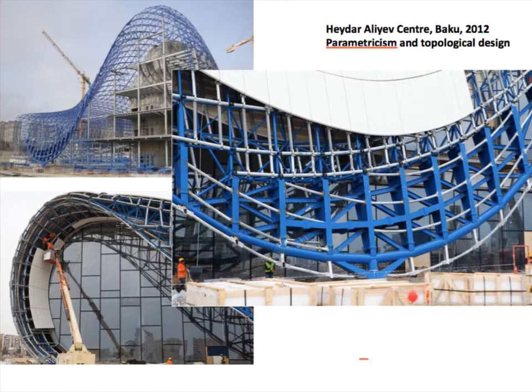It is, however, made from steel, a material that is around 7 times stronger than reinforced concrete. If it had been made in reinforced concrete, as the CNIT shell was, the equivalent thickness would have been 420 millimeters, and the ratio would be more like 71, which would put it in the same efficiency category as the Sydney Opera House. In view of the variety of structural components involved, the structure is also typological rather than topological,